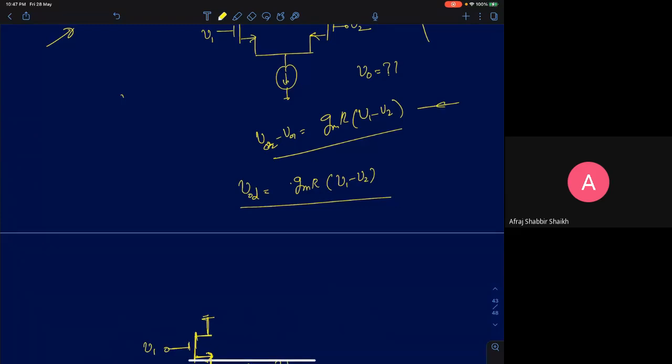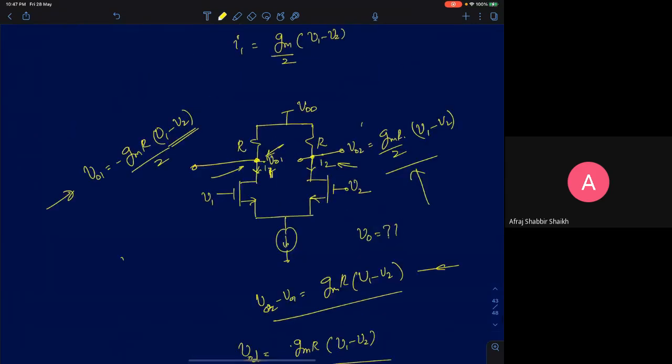So here I have a circuit, even if I take the output single-ended, if I take the output at this node, this circuit will give me a voltage which is proportional to the difference between the two input voltages. So I can directly use my current biased differential pair to generate the difference of two voltages.